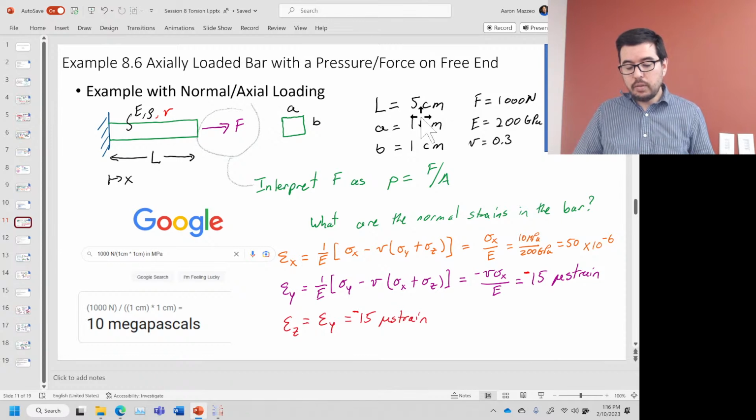So if we multiply these two against each other, that's 0.05 times 50, all right, that cranks us up to 200, or 5 times 50 would be 250. And then we have to move over a little bit, 2 zeros. So that actually takes us to about 2.5 microns. Okay, I did that calculation pretty fast, but 5 centimeters times 50 microstrain should be 2.5 microns.